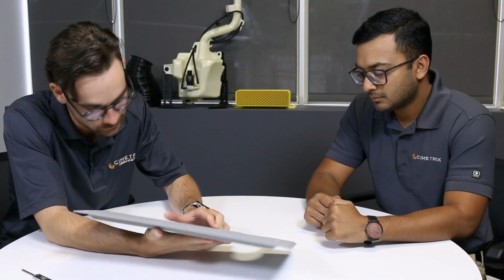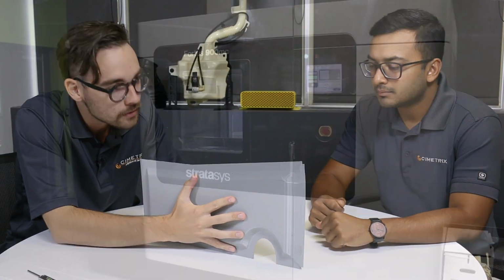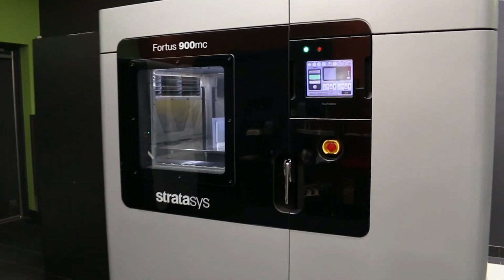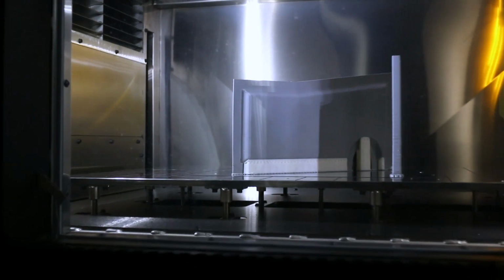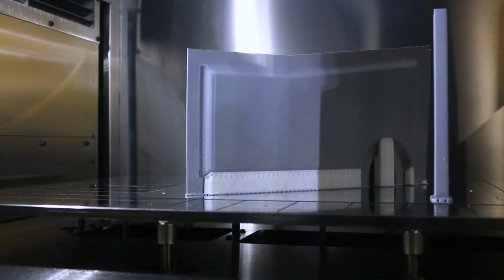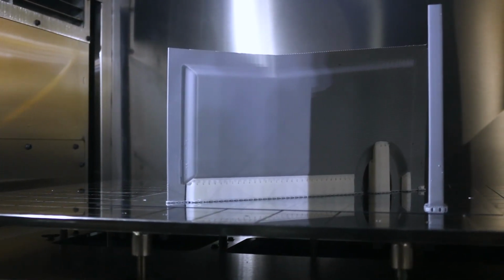Typically for low-fidelity prototyping, we'll work with a thicker slice height and a more cost-effective material, such as ABS or ASA. For our low-fidelity prototyping stage, we're less concerned with material performance and material strength, and mostly concerned with near-net shape and mating with assembly features.